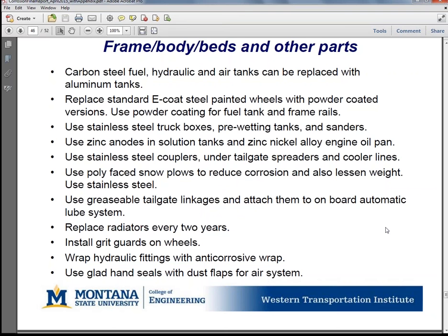Well, typically, in my opinion, it would be probably easier to just use a zinc-rich coating. So basically, what it does is the zinc will sacrifice itself to protect the underlying substrate, say if it's a steel. But in their case, because the acid solution tanks have so much corrosion, they think the zinc-rich coating is not fast enough, so they actually distribute zinc anodes, and it seemed to work. But we can certainly follow up with Oregon to get more details. They have some detailed configuration, how they did it exactly.